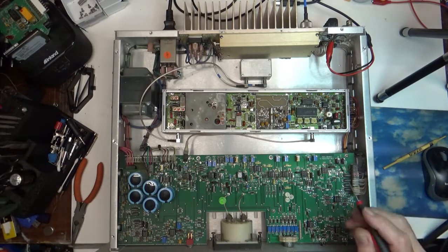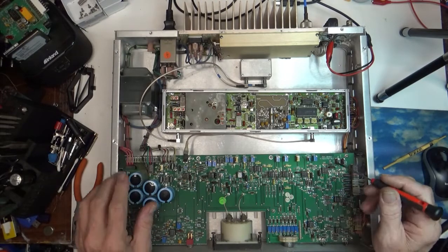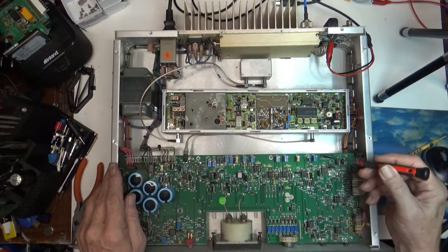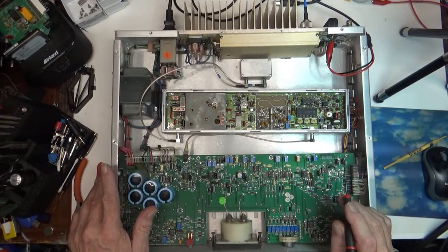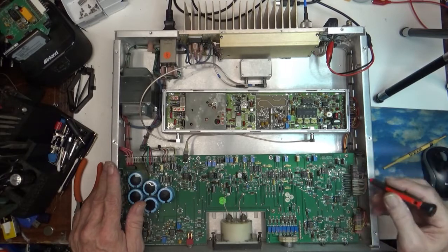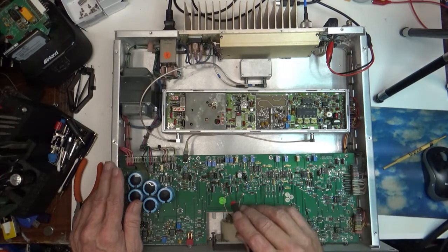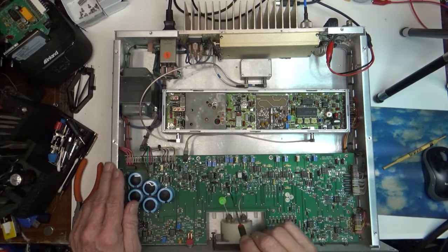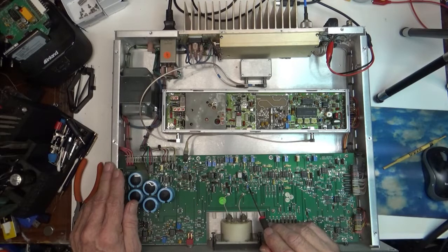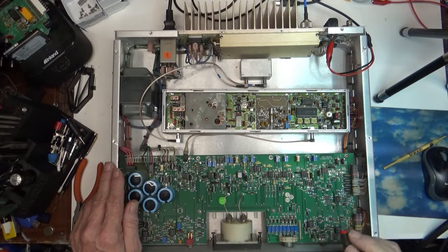When you switch these things over, let's turn the transmitter off, that's good. You've got a bunch of little jumpers that you have to play with here, and they're all marked. Here's mono and composite. Here's your phase select, that doesn't count. Mono and composite here. This is your low pass filter. We use that, it stays in.